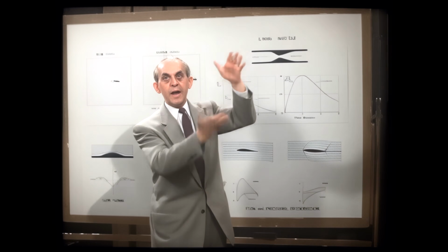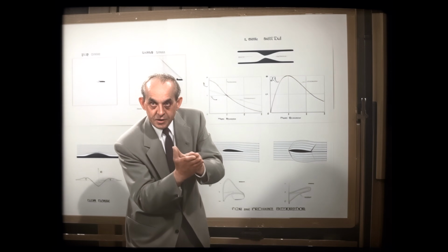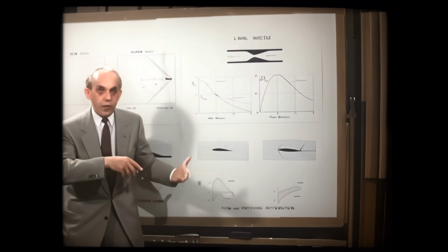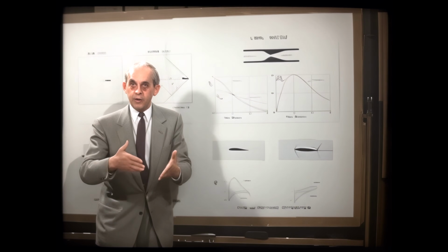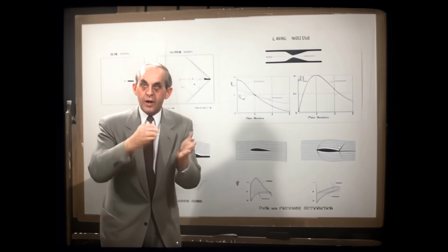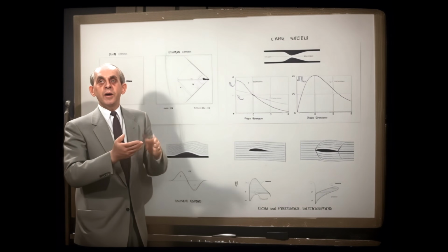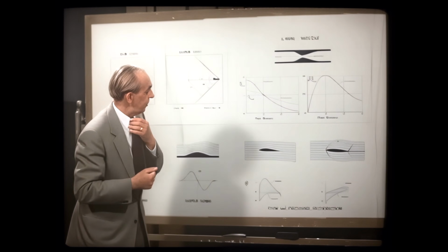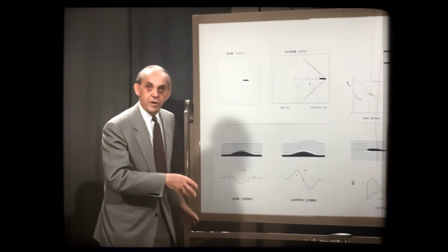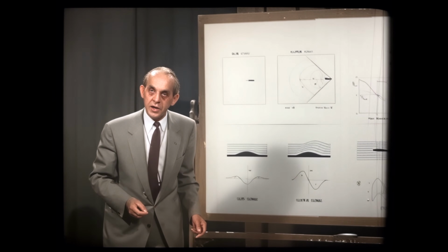And in the supersonic range, acceleration means a widening of the streamlines, and deceleration gets the streamlines nearer together. In the subsonic range, it's just reversed, as we know, because when we want to make more speed, then the streamlines have to come nearer together. And diffusion means deceleration. Therefore, all these geometries of the flow fields are completely changed.